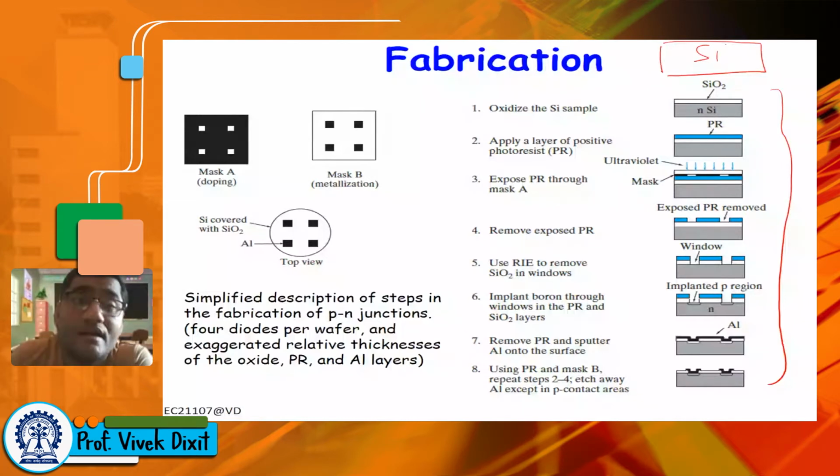So with that sample, a beginning sample can be N-type or P-type. At least in this example, it is N-type. Now, if you want to form a diode, what do we have to do? We have to make a P-type silicon here, right? One way, of course, is we take this piece of semiconductor and somehow inject holes from the top, then the whole upper layer will become P-type.